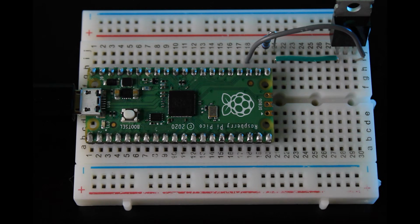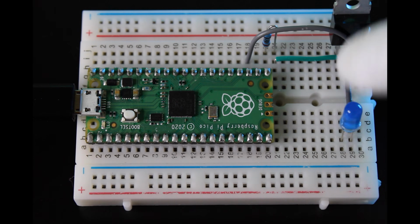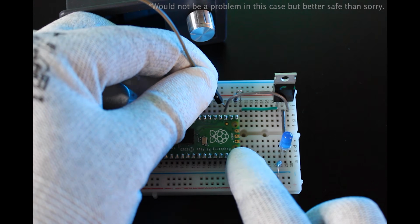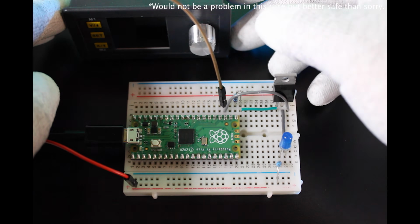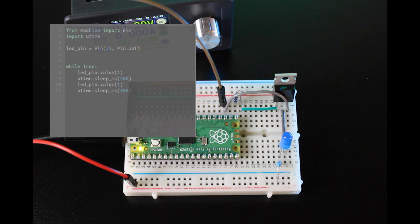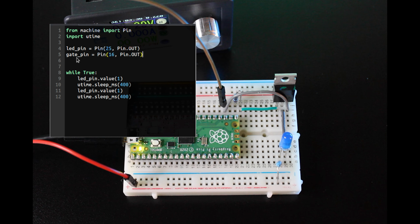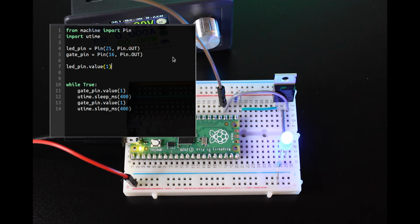And what the MOSFET is now doing is controlling this external LED. So instead of using the internal one, we are now using an output pin. We also need an external power supply to not exceed the ampere limit of the output pin. And we have to modify the code as follows. We're introducing a new pin, and now we are switching the LED pin to the external pin. We rerun the code, and now we're controlling an external pin, in this case this LED here.